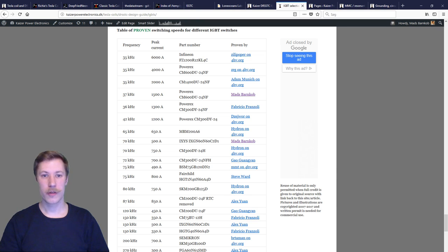Because I would assume that you can push almost any IGBT to double, but the wear and tear on the IGBT die itself and the bonding wires inside the IGBT gets very high when we get into the extremities of current switching. So again, this comes down to how long we want this to live. I have seen a lot of IGBTs inside where the silicone gel is cooked or charred, or you can really see that it has taken some damage due to heat.